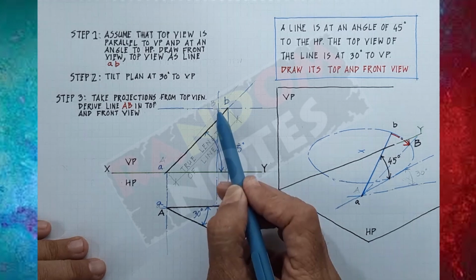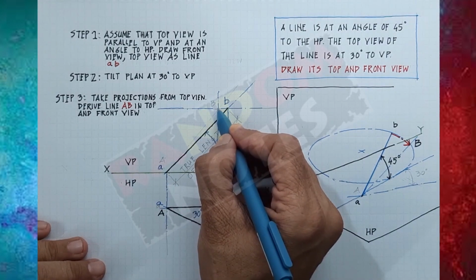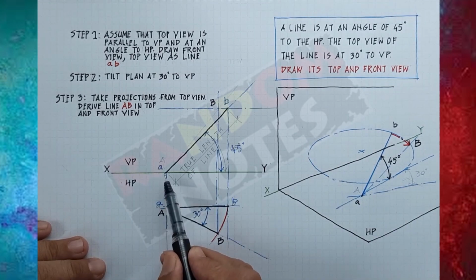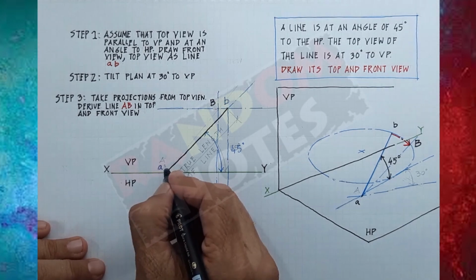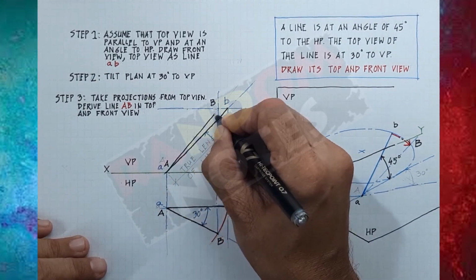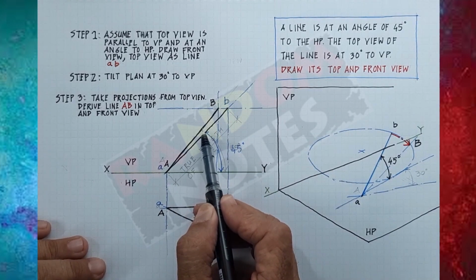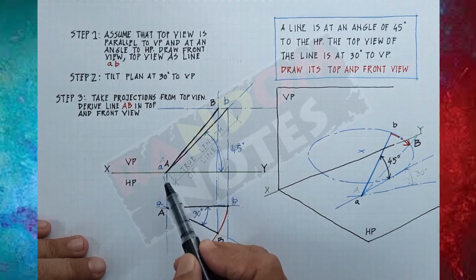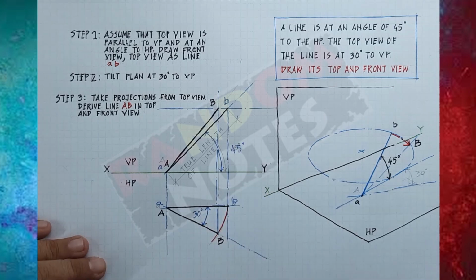Wherever this projection cuts this horizontal line, that gives me the actual point B. Since point A has not changed place, it is anchored at this point only, so this will be point A. And now this line is the true front view of the line AB, which we have named as capital A, capital B.